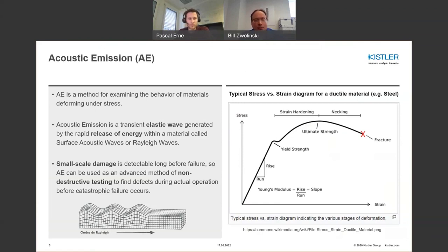measure ultrasonic signatures that represent certain conditions of the material. And that's really what the AE, the acoustic emission sensor, is doing. It's allowing us to get advanced information on materials, how they're being affected by various processes, and that way we can use that information to better estimate failure or when they need to be maintained.